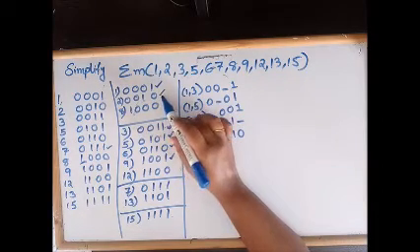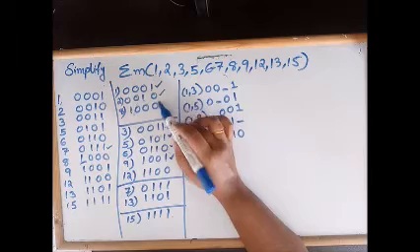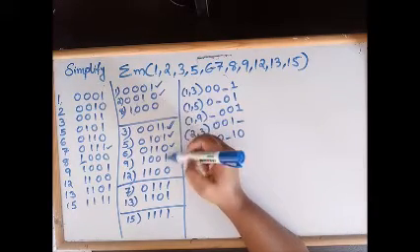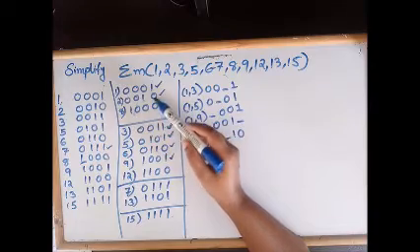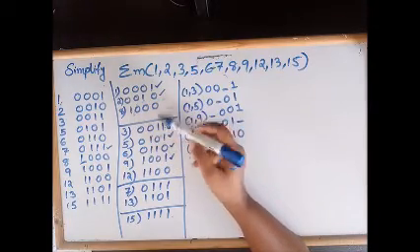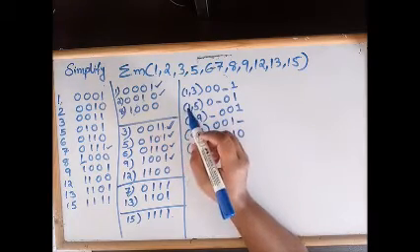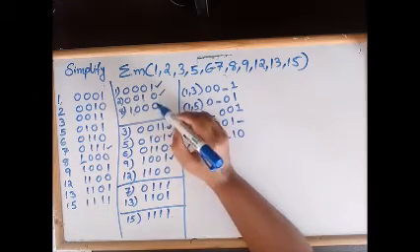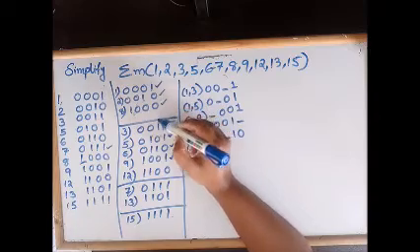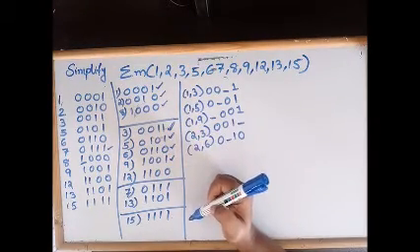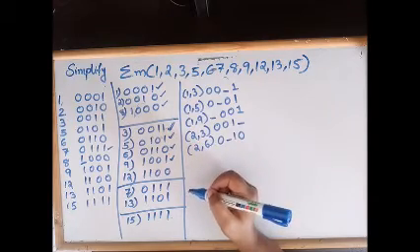Again we can check with 2 and 9. Again we cannot combine, more than one bit difference. In 2 and 12 also more than one difference. Okay, so what is the next option? We take the next element from the first group and again compare with all the other terms in the second group. So follow the same procedure. You will get